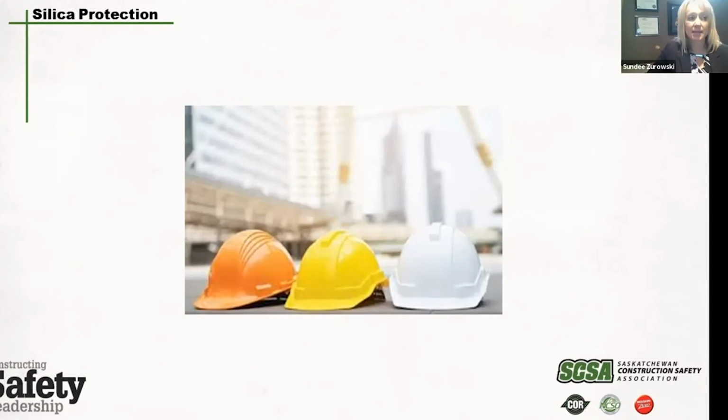Employees can help protect themselves by changing out of your work clothes before going home, and participating in the training, exposure monitoring, health screening, and surveillance programs to monitor any adverse health effects caused by exposures. Be aware of the work practices and tasks that create exposures. Be aware of the health hazards and that smoking adds to lung damage caused by silica exposures. Hygiene: workers must not eat, drink, or use tobacco products in areas contaminated by crystalline silica.